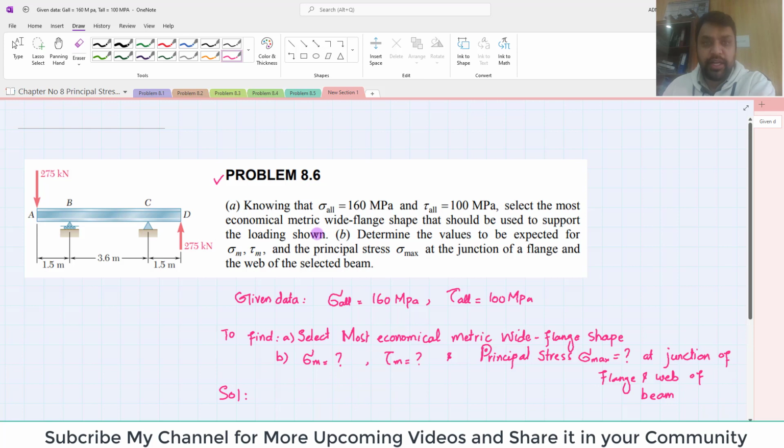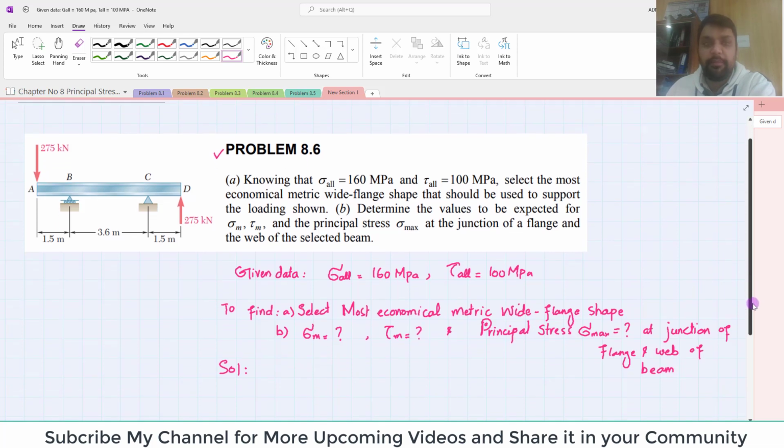Clear? So you have to select the most economical wide-flange beam for the allowable normal stress and allowable shearing stress. Also find the value expected for maximum bending stress, maximum shearing stress, and the principal stress at the junction of flange and web of the selected beam. This is the given data. I have written them, and we have to find the most economical wide-flange shape, and in part B, the maximum bending stress, maximum shear stress, and principal stress at the junction of web and flange.